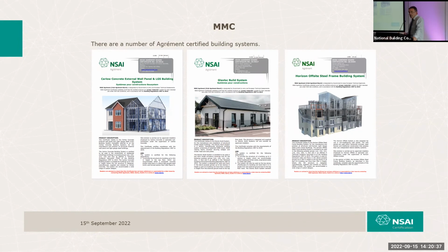See a lot of these problems now in podium slabs, where you've got big, meaty, 650 deep reinforced concrete podium slabs, which transfer a car parking grid to a grid more suitable to apartments, and massive thermal bridges there. So how do we get around those? We need to approach that at early design stage. Maybe the right solution is to go with insulation on top of that podium slab and a screed zone. But those things need to be done early doors.